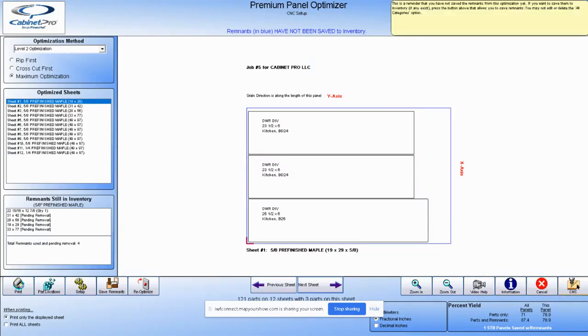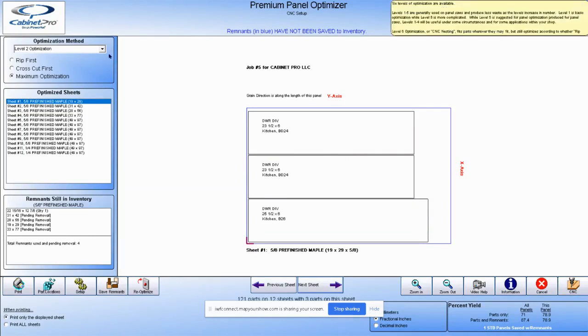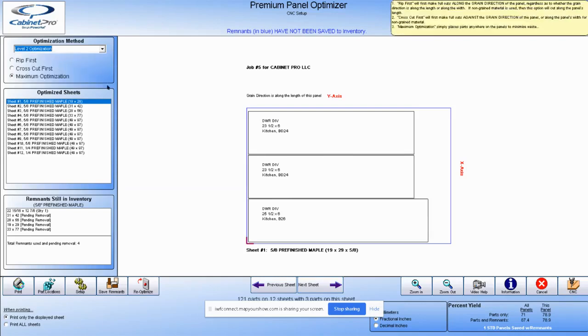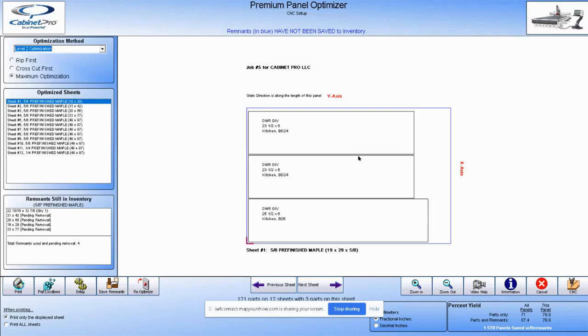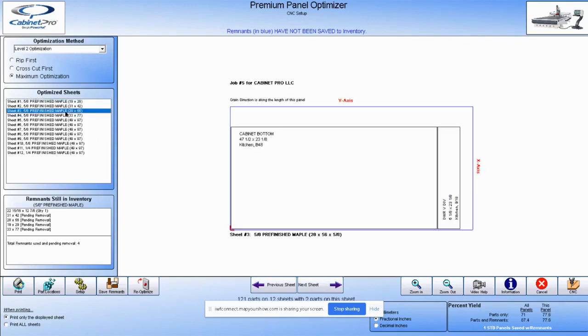And if you say, okay, let's say we go to the CNC router, or we want to cut these out on a panel saw, well, not actually these, because if we go to the CNC router, then it'll take those out of inventory permanently. Now, because I chose levels 1, somewhere between levels 1 and 5, which is for a panel saw, it automatically switched from a tool for the CNC router to your saw curve that you set up in here.